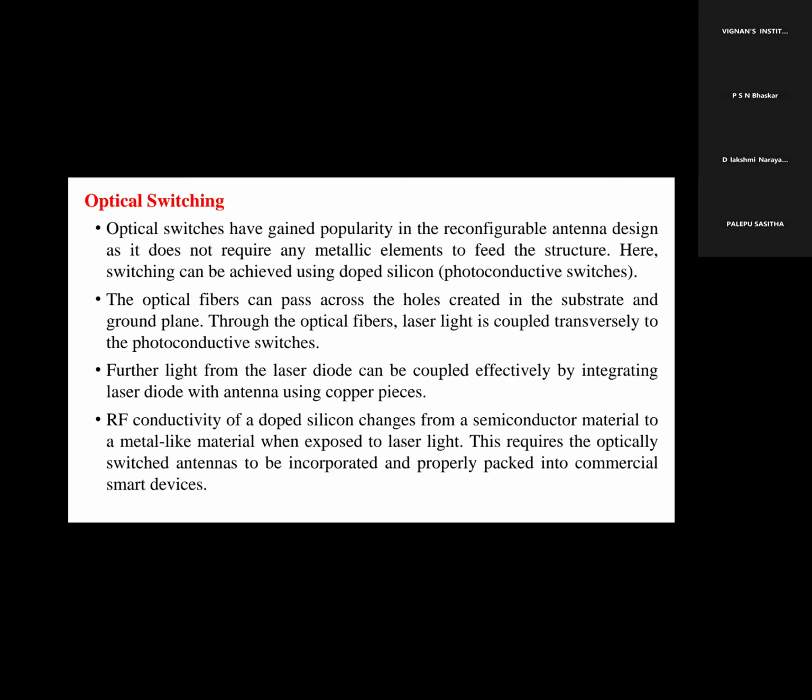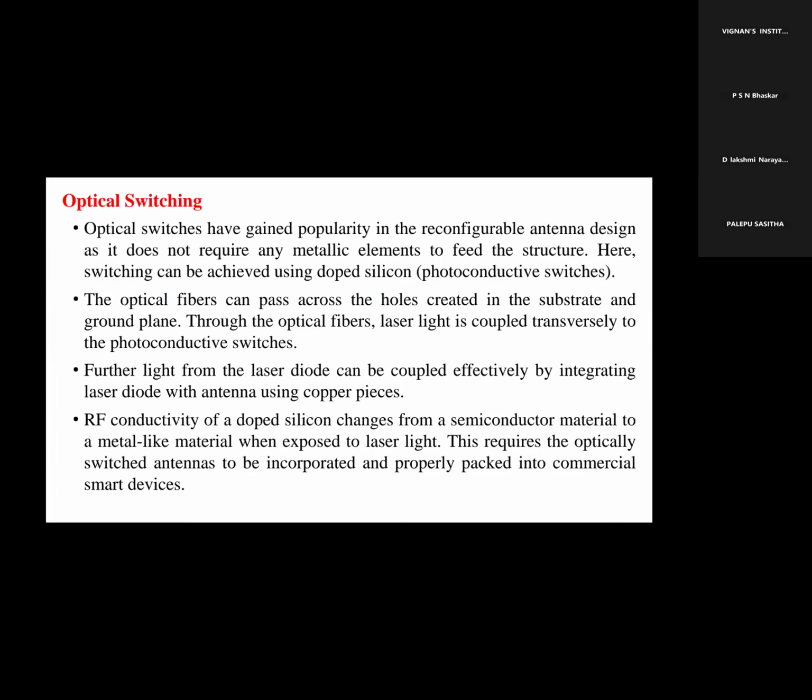Optical switches have gained popularity in reconfiguration and design as they do not require any metallic element to feed the structure. Here the switching can be achieved using doped silicon, meaning photoconductive switches. The optical fiber can pass across the holes created in the substrate and ground plane. Through the optical fiber, the laser light is coupled transversely to the photoconductive switches. Further, light from the laser diode can be coupled effectively by integrating the laser diode with the antenna using copper pieces.